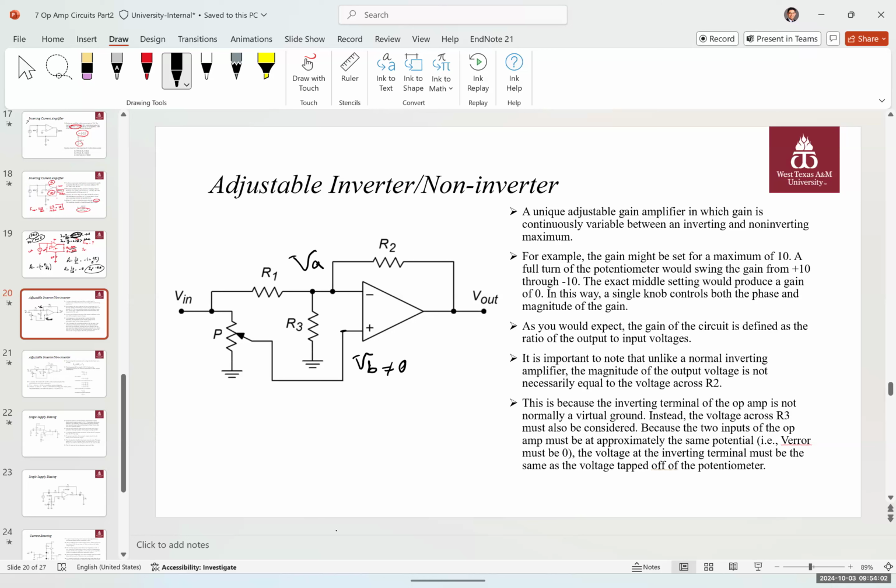If I have two signals, I can give a signal to this. It's creating the inverting signal with the same thing. And if I add these two together, I'm going to have a zero. And if you want to tune down the noise canceling part, you can adjust the potentiometer to go from inverting to non-inverting, and then you can amplify it from zero to an inverting or non-inverting. So this is one application.